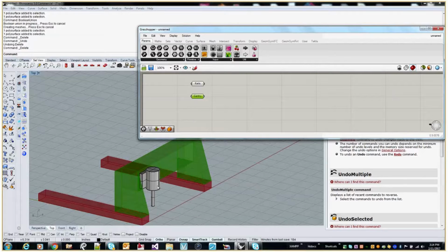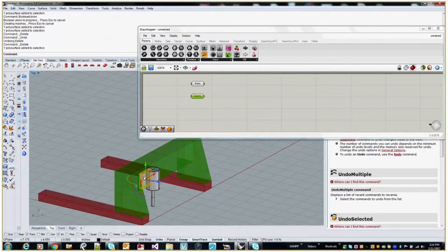Okay, the other 2 main parts that I have here are what I'm going to call the Z plate. It's the plate that will move in X, but it will normally have some big fixture up above or whatever with a motor and a lead screw that will drive this motor and tool up and down in the Z-axis. So I didn't draw all the motors and that sort of stuff for ease of whatever, but just realize that this is representative of that, and you should be able to apply it to your specific need.